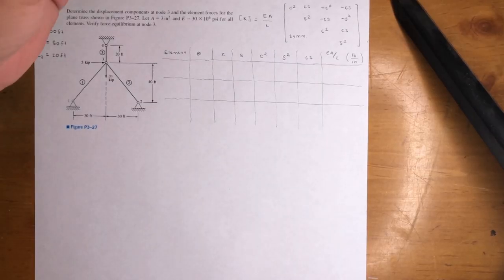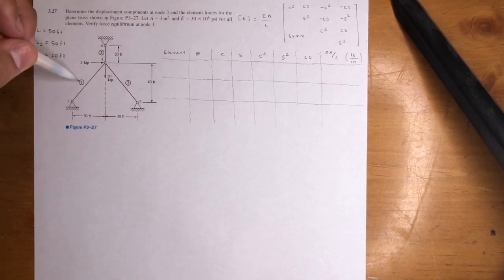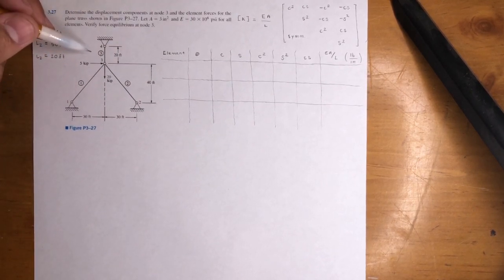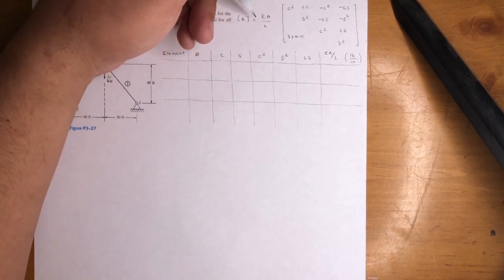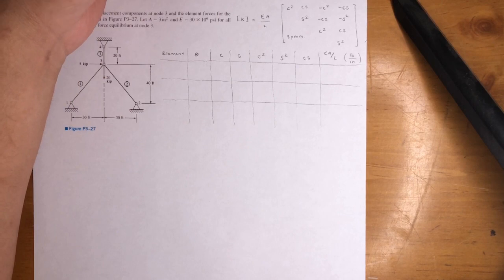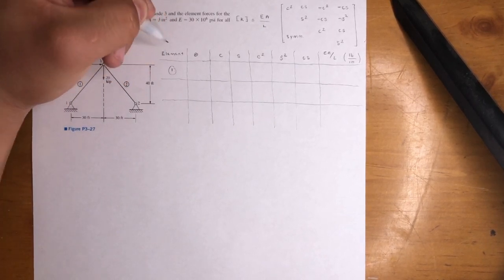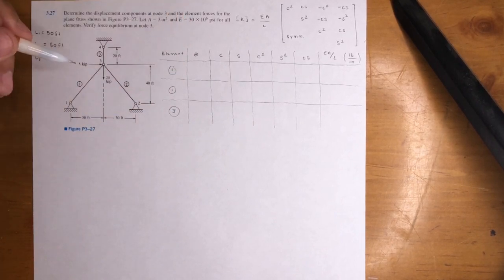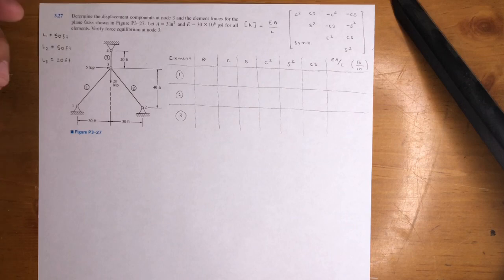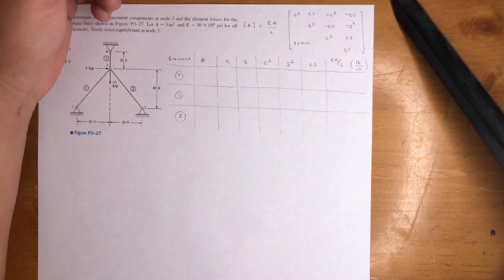All right, so I want to go ahead and write all these out, right? So this is the stiffness matrix we're going to use for each element, and then later assemble all three of them. In this case, we've got 3 elements. So we're going to use these little stiffness matrices to make the big global stiffness matrix. And then the table, right? So we have 3 elements, 1, 2, and 3, which are just the bars, and we've got to get all these values for each one to fill in this matrix. And yeah, that's pretty much it.